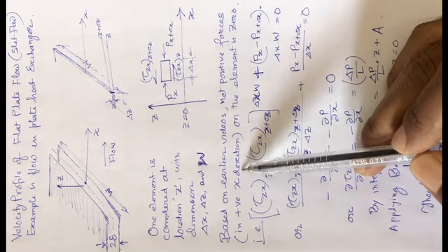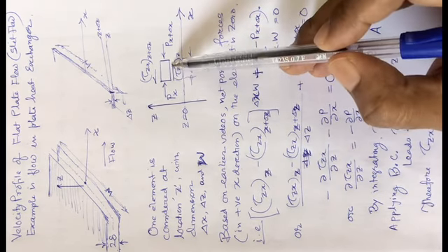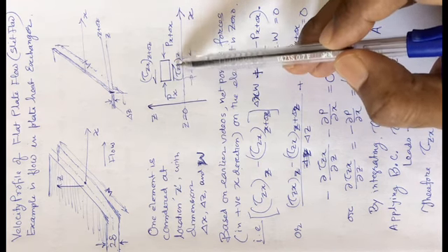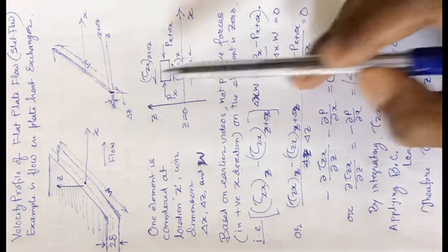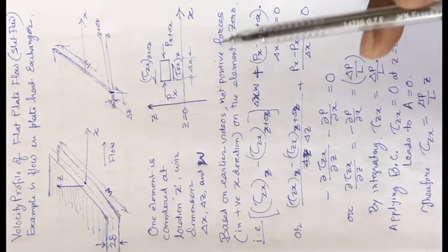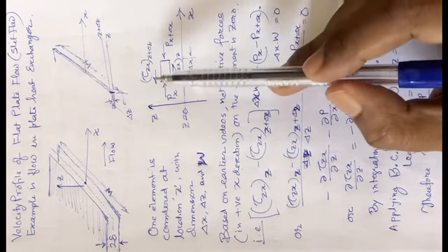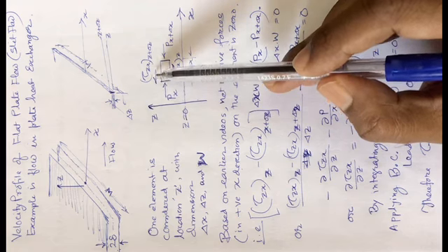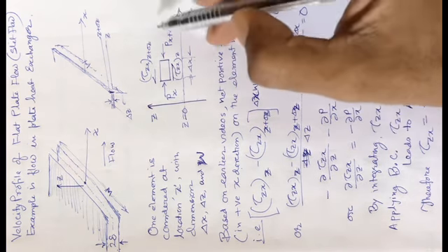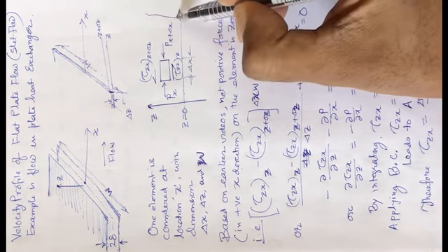In the positive z direction, the higher positive shear stress will be acting in this direction, and at location z plus delta z it will be acting in the opposite direction, because we are expecting the velocity profile to be like this.